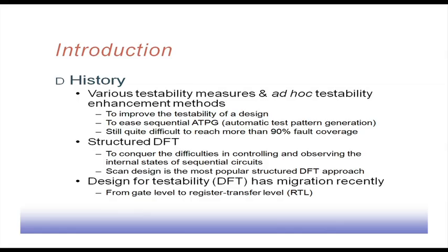That gives rise to structured DFT. We want to conquer the difficulties in controlling and observing internal states of sequential circuits. Sequential circuits are a major concern, because for testing a particular fault, we need to apply some pattern to the internal flip flops.